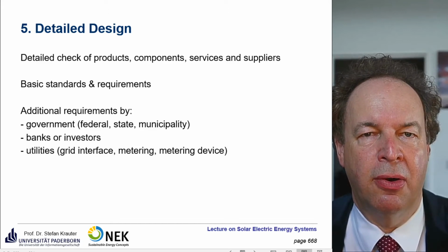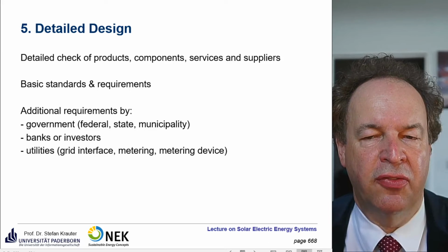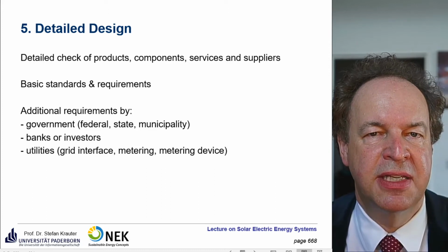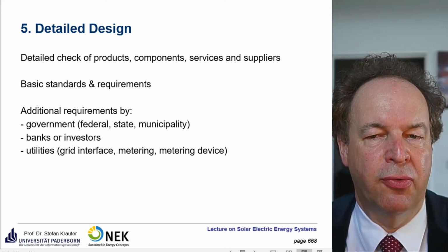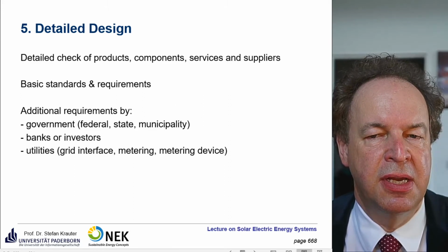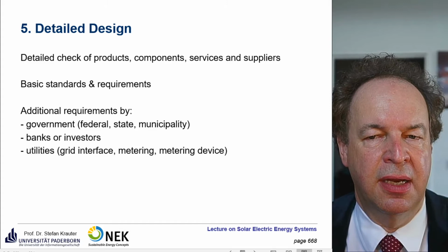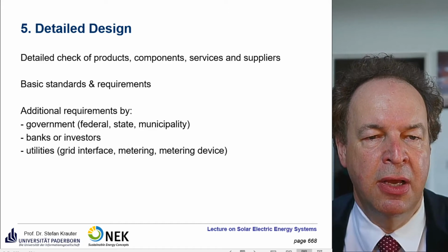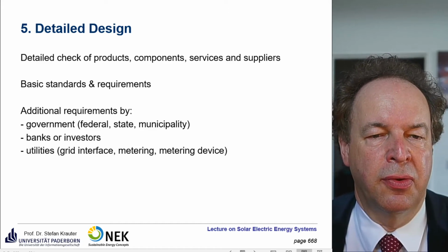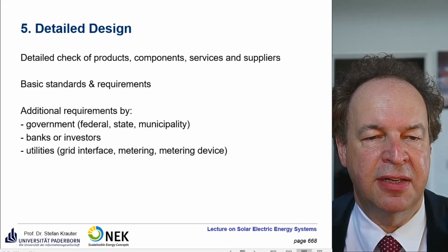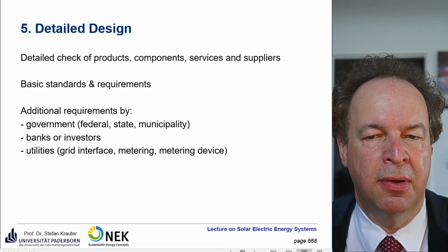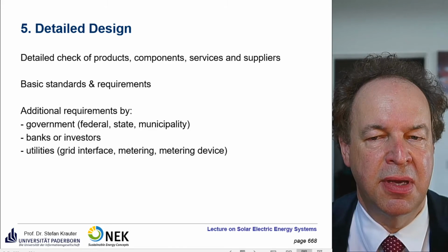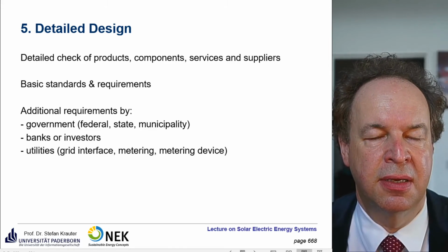Will you be paid then, or do you have to immediately shut off the power plant? Sometimes there's a regulation with fault ride-through. So the power plant keeps up operation for some milliseconds, just to override a power failure, and then helps to keep the grid running. Also for metering, you have to make sure that the meters are all certified and calibrated. Sometimes there are even requirements that you have to choose locally produced metering devices, so they are sure that the metering is correct.